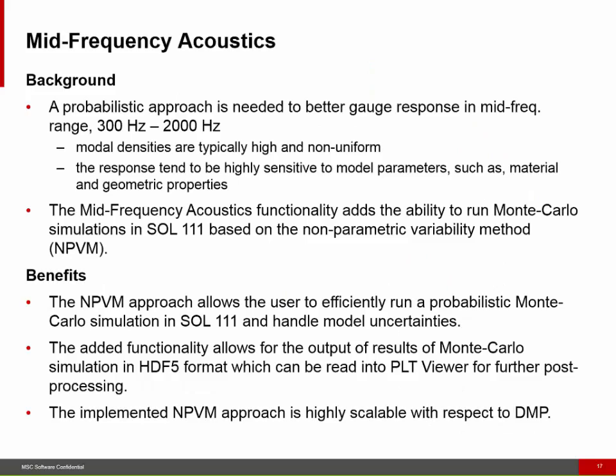Moving on to the next topic, which is mid-frequency acoustics. When performing modal, dynamic and acoustic simulations in the mid-frequency interval, it can be from 200-300 Hz up to 1 or 2 kHz, the modal density starts to get really high and the modes are much less separated.